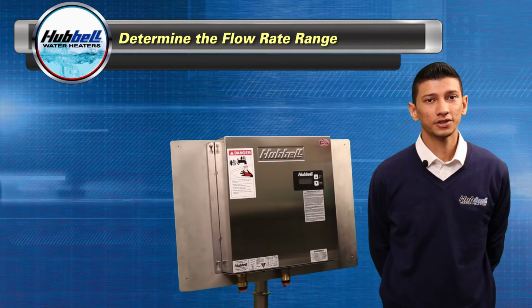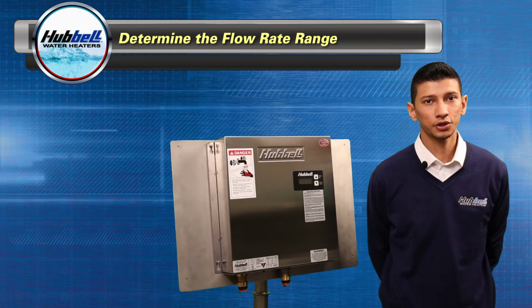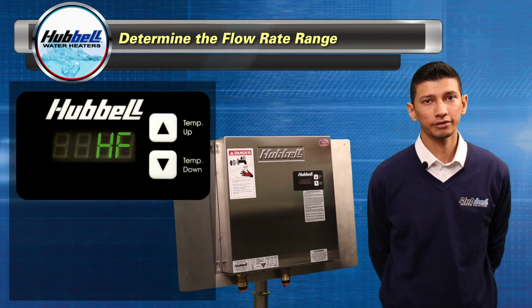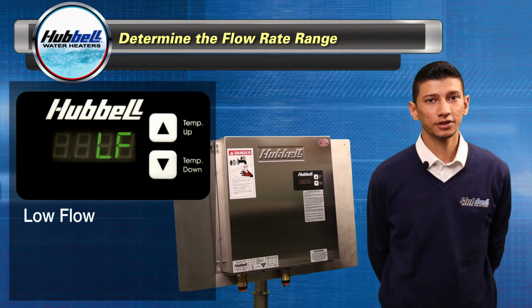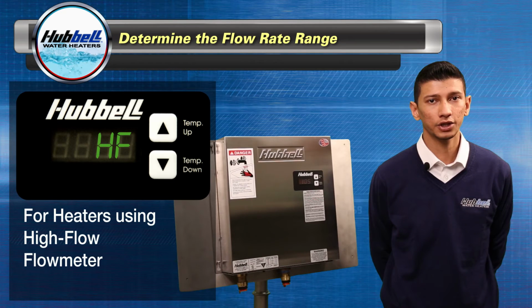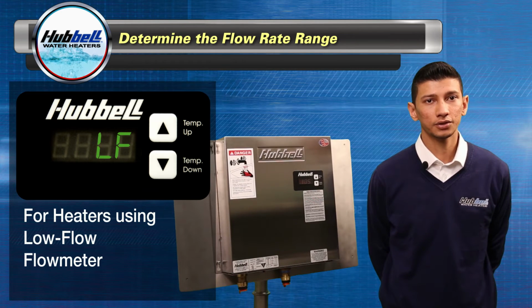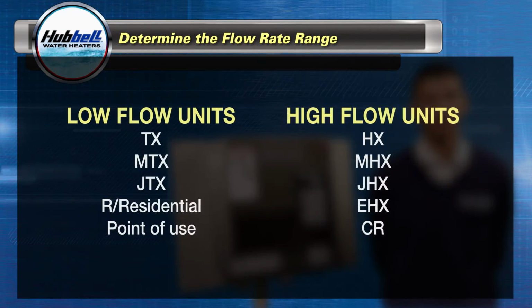The next parameter is used to determine the potential flow rate range the heater will see. There are 2 parameter values: HF for high flow and LF for low flow. If your heater uses a high flow flow meter, the parameter should be programmed for HF. If your heater uses a low flow flow meter, the parameter should be programmed for LF. Here's a list of our high flow and low flow units.